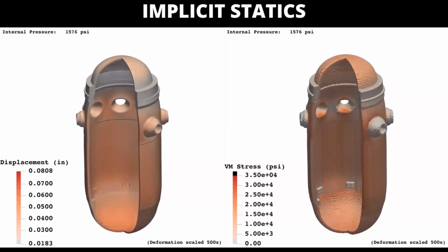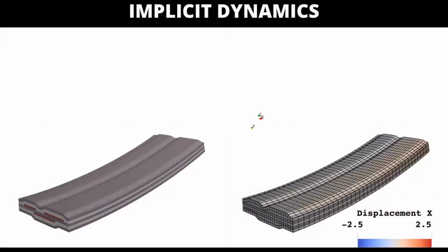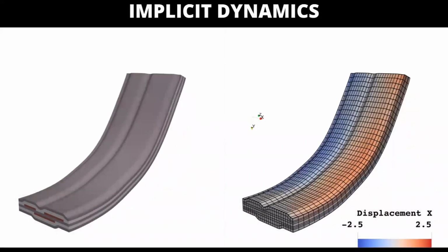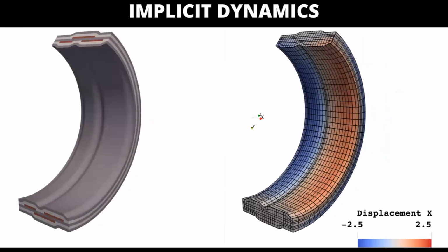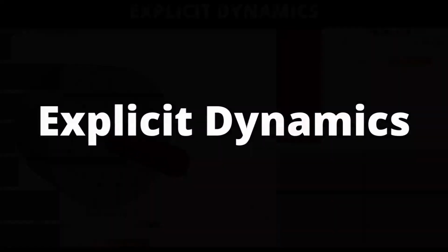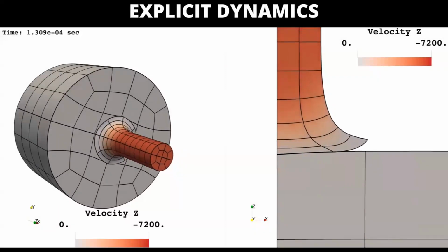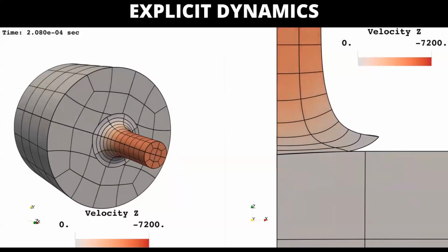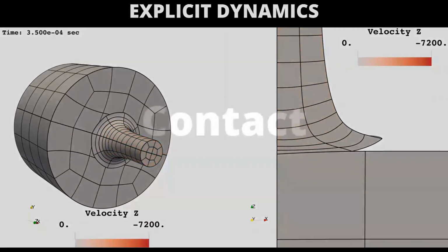In this case, we're looking at a reactor pressure vessel and trying to detect whether or not at load pressure we'd have plastic strain. We also support implicit dynamics. So here, each frame is a time step taken with an implicit midpoint time stepping method. So really large time steps. But we can also run explicit dynamics analyses for cases where maybe it doesn't make sense to take really large time steps. So you can see here a model of a Taylor impact.